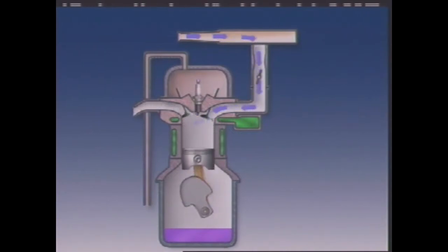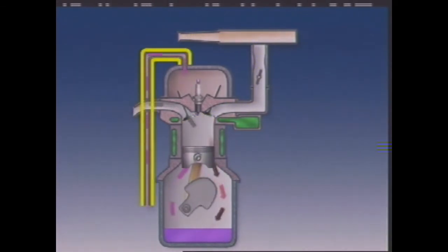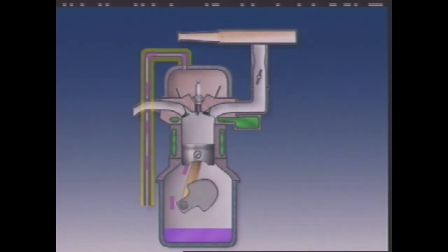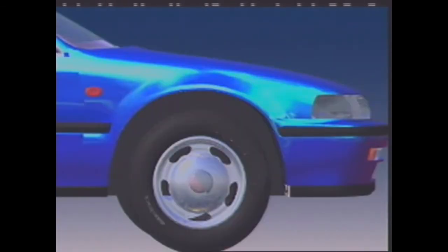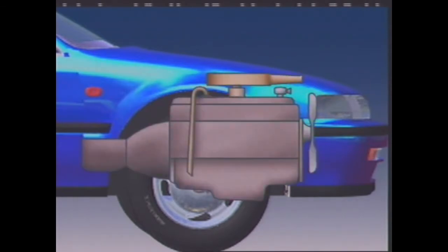When the engine reaches its full operating temperature, the water and fuel evaporate. To prevent pressure buildup, the crankcase must be ventilated. In older vehicles, crankcase vapors were vented directly to the atmosphere through a breather tube or road draft tube. It was shaped to help draw the vapors from the crankcase as the vehicle was being driven.